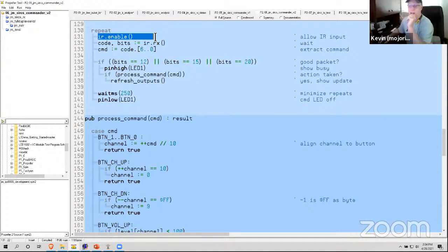All right, thanks. The Sony remote. Now with the tagger, this is a little bit different, because we're using Sony IR bits, but we're not using the Sony IR protocol. What I was saying earlier, there's kind of 3 things that we can do. I press the trigger, we shoot a packet. That's 15 bits. Now this is a legacy thing that I had to match up from the old system.